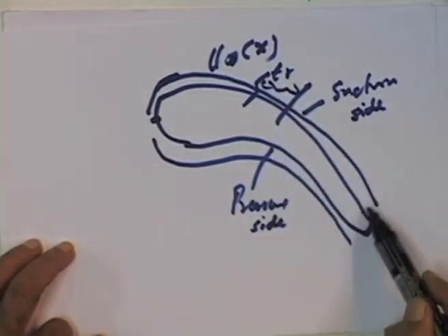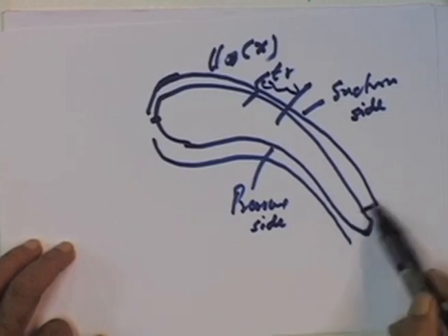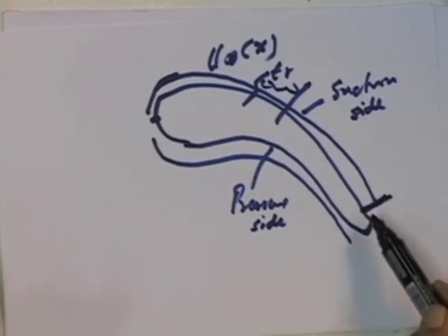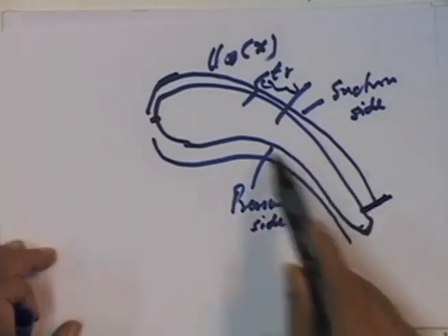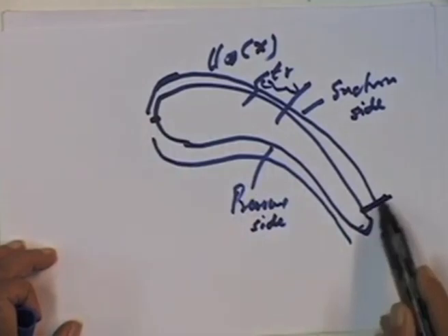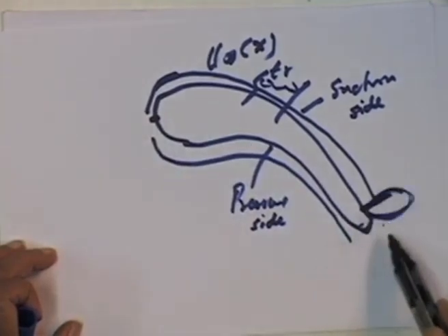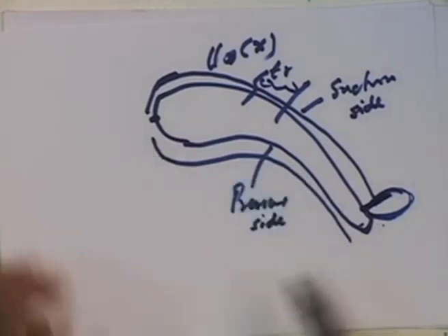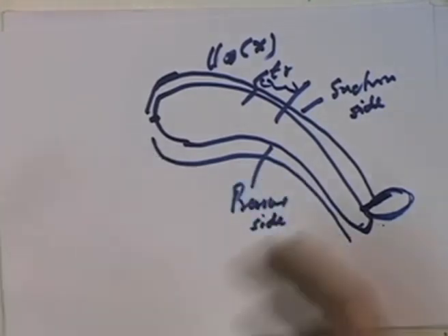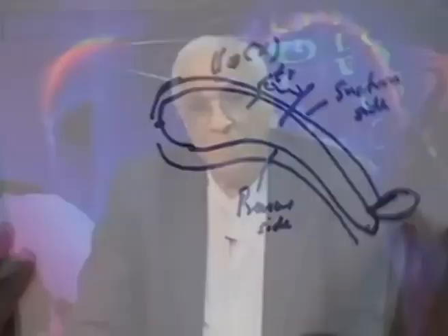And should any separation occur, then of course, that is undesirable and therefore, one would like to adjust the shape of the blade in such a way that no separation is found near the trailing edge. One can do the same on the pressure side. So, calculations of this type have been used in the pre-CFD days. These type of calculations were extensively used to design and shape the compressor and turbine blades.